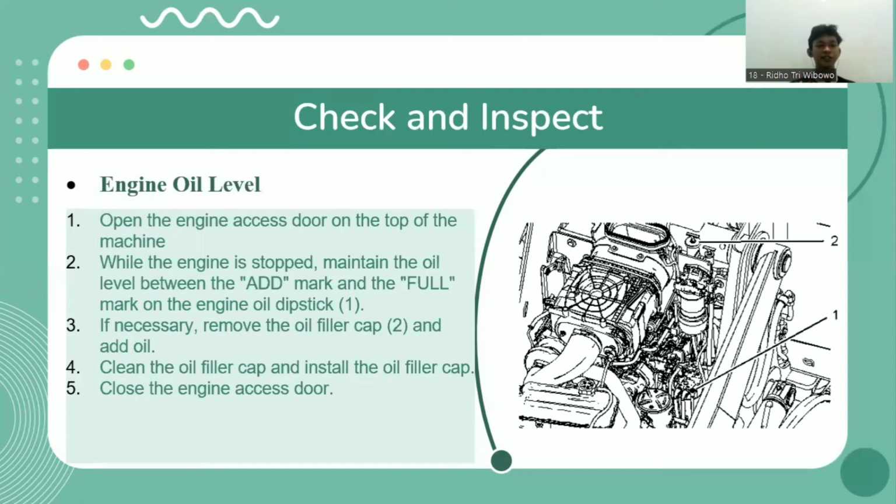Third, if necessary, remove the oil filler cap. Number two, you can see in the picture, and add oil. Number four, clean the oil filler cap and install the oil filler cap. Number five, close the engine access door.